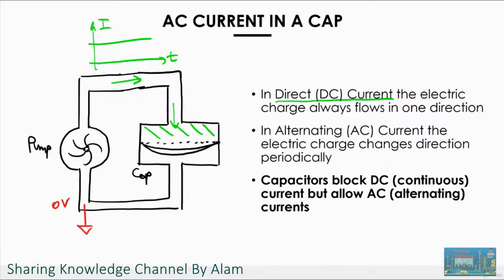And if we are forcing a current that has this shape, that is constant and forever a positive value, that means the membrane will have to continue to stretch. Now it's easy to see how this is not possible to sustain indefinitely, and eventually the membrane will break. And this is exactly what happens also in electric circuits. If you try to force a DC current into a capacitor, the voltage across the capacitor will keep increasing, and eventually you'll break the device.